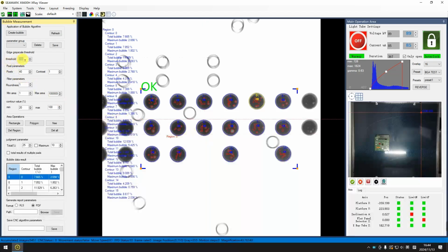And then we need to set the value over 30%, like 210, for example. And you will see it will recognize the edge more accurately than before. You see, if I change it to 100, it will reduce the error, right? So if I set it back to 210, you see the edge is recognized better.